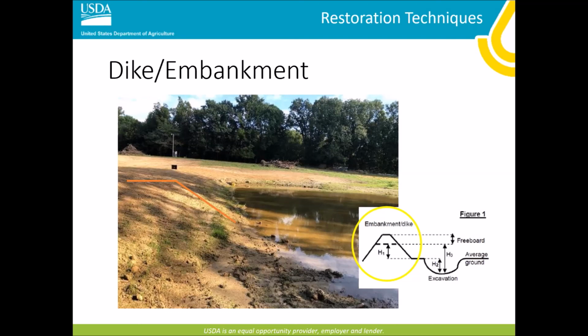Another one is our specs, our engineering specs that we have on it, or our conservation specs. Say, okay, we can't have more than 30 inches of excavation. Okay, we can't have any more depth than 60 inches of water. So that leaves us about, in some cases, 30 inches of embankment height to work with.